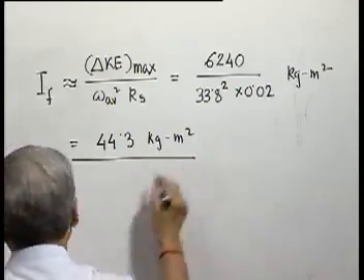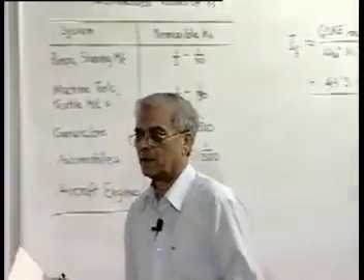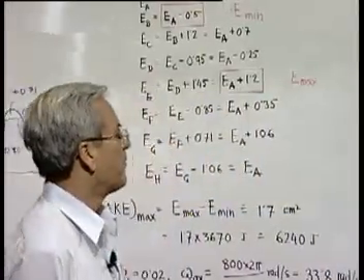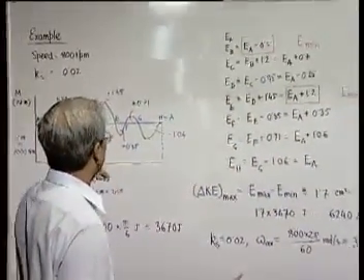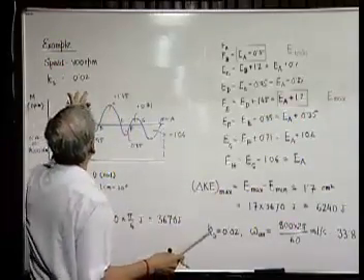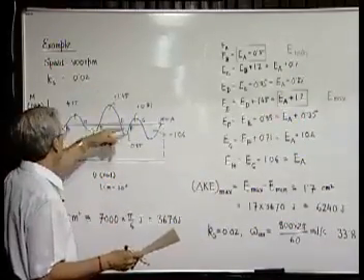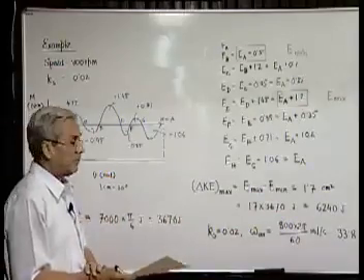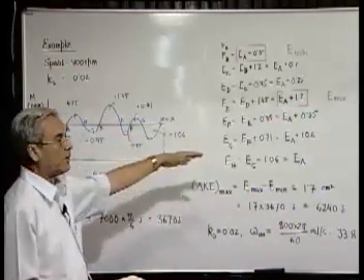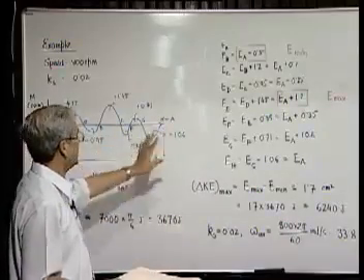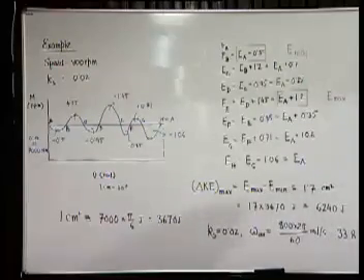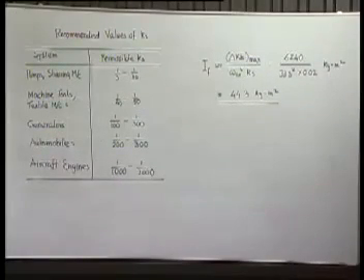so if we attach a flywheel with this much of moment of inertia, then the fluctuation of speed will definitely be contained within 2% when the engine runs at 800 rpm and when the fluctuation of energy or the turning moment diagram of this multi-cylinder engine is as specified. Let us now take up another example which is of the other type.